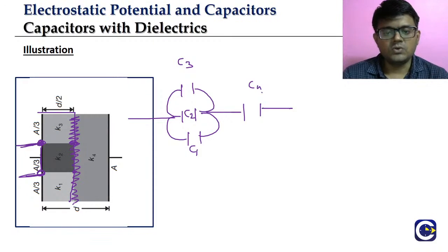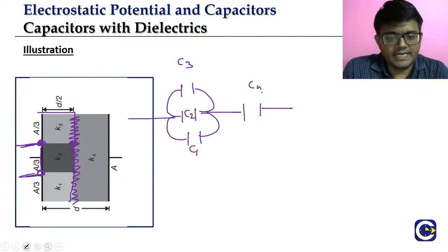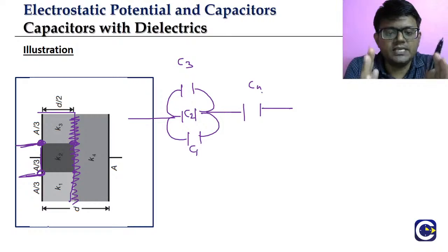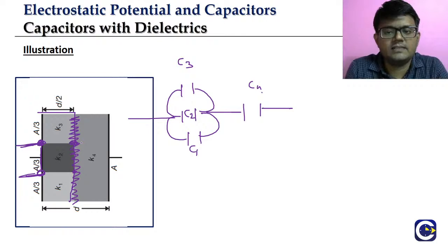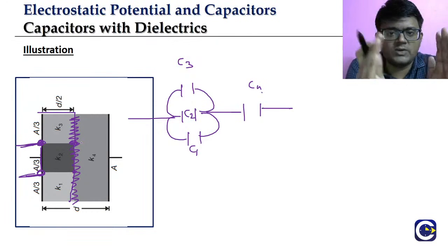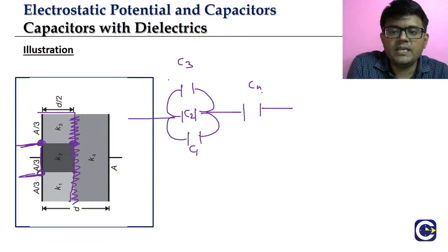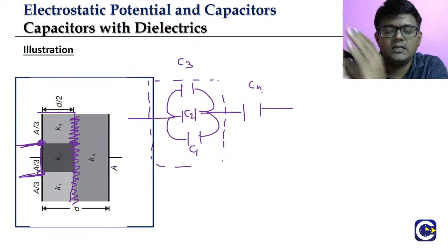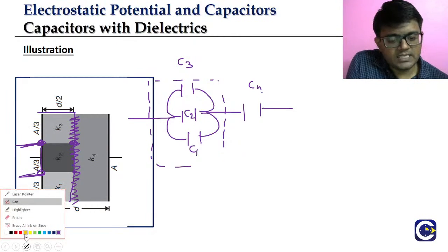Okay? So this is the main important thing. Once you are able to get it right, we need to be thinking about why it comes like this. Because C3, C2, C1 are like terminals connected, so they are parallel. Next to that entire parallel arrangement, we have C4 kept in series. So C4 will be in series with this particular branch, with this full parallel block. Okay? So this is the main important step. Once this is done, we are able to get the answer.